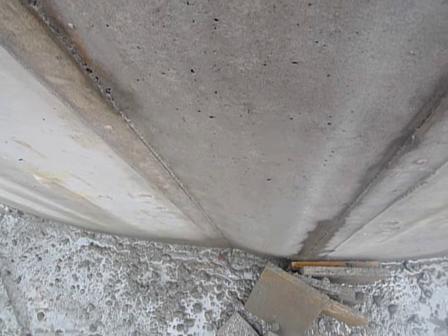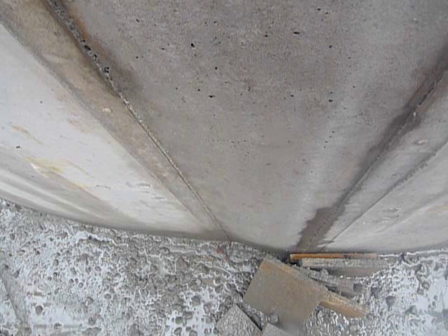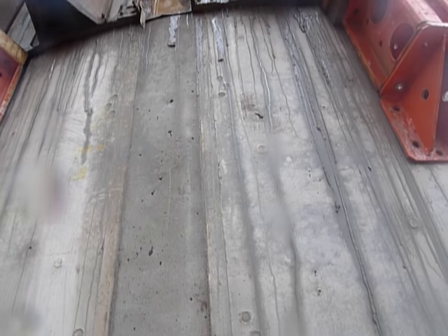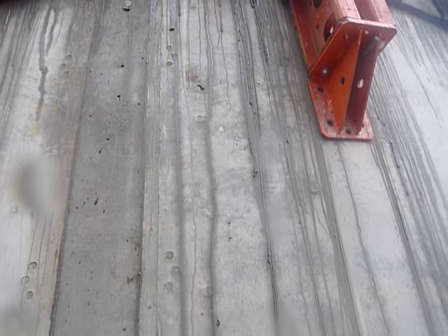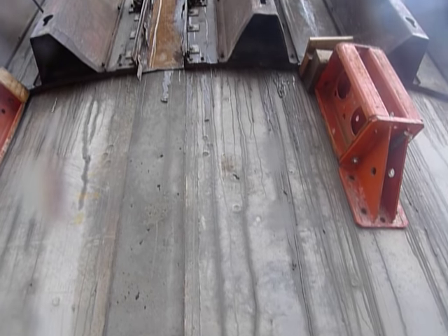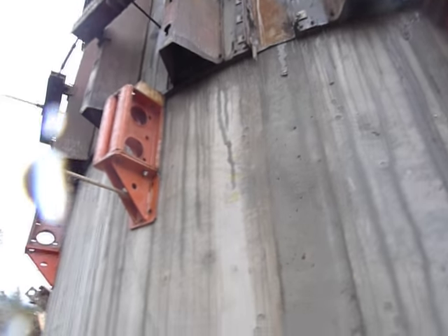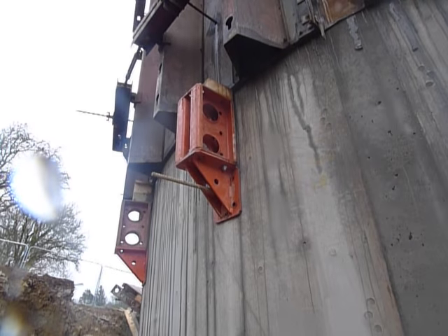It looks a little bit worse maybe as I'm looking at it on the camera here. It actually works out at about 8mm. So we basically ended up with the bottom part of a wall 8mm thicker at one point, and then as we went up, because there's no weight on the top of the concrete, it's back to its normal correct alignment. If that had replicated itself up there, we'd have expected the shutter to have given a bit of grout loss. It hasn't, and it's been very good in that respect, so there's no problems with it.